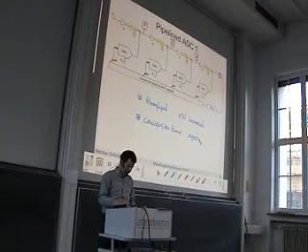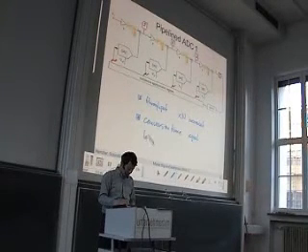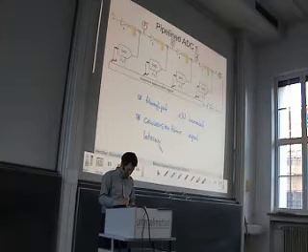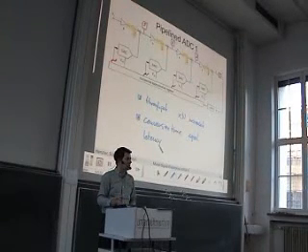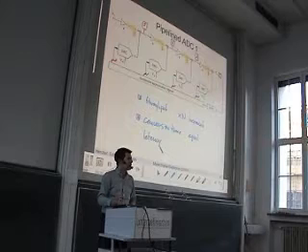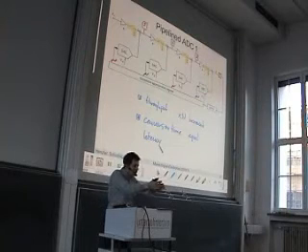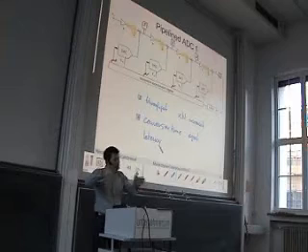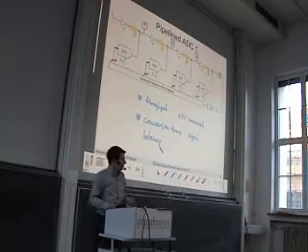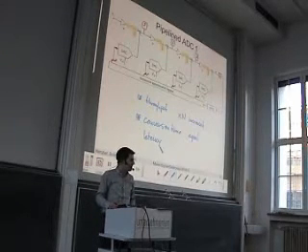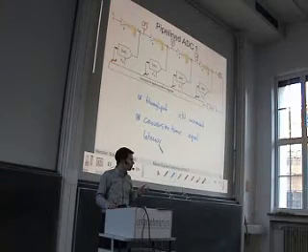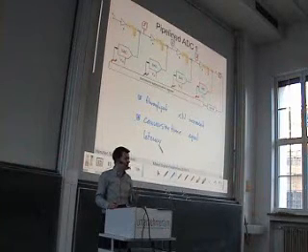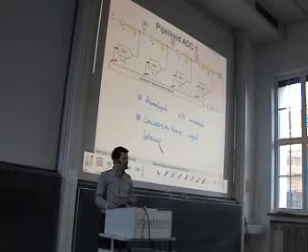People also say there is a latency along this pipeline or in this converter, because after applying data at the input it takes n cycles, but after each cycle new data comes out. So is it clear here the difference between throughput and latency or conversion time?